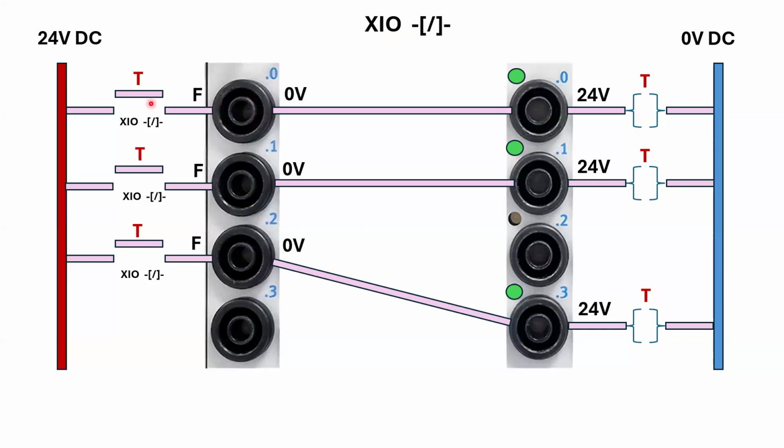So now we have instruction that's examine if open, if we have that over here. And just like we did in the beginning, we analyzed that. So examine if is it open. Well, yes, it's open. So that is going to translate into the false here. See, this is where things are getting a little bit complex. This is going to give us a false state.